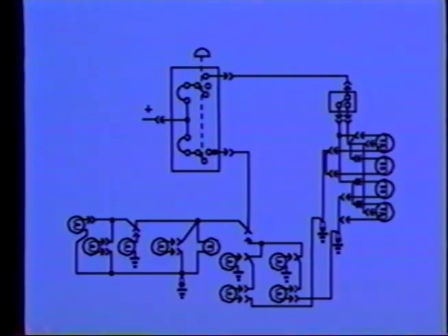Using the same schematic, you can consider this. In the circuit shown, all lights operate correctly except the tail lights and the rear side marker lights. The most likely cause of this is A, open in feed E, B, open in feed A, C, open in ground 2, D, all tail light and rear marker lights are blown.